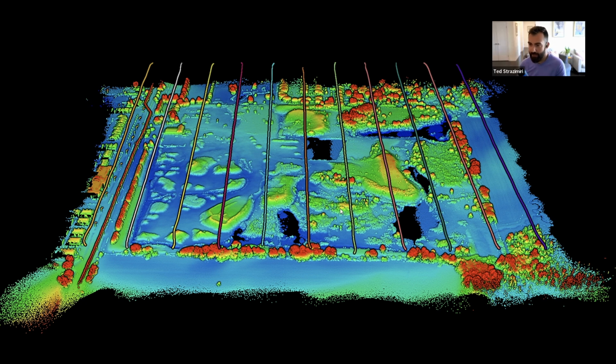And I can't really see a situation, unless I really want to cover a very large area very quickly, to fly at 400 feet or the maximum altitude that you can fly in your area. The laser in this payload, on the spec sheet, says it's good to like 300 meters, so well above what you would be flying a drone typically. But that doesn't mean that you need to be flying at that altitude, or that at that altitude it will be the same kind of results that you see at the 80 to 90 meter.